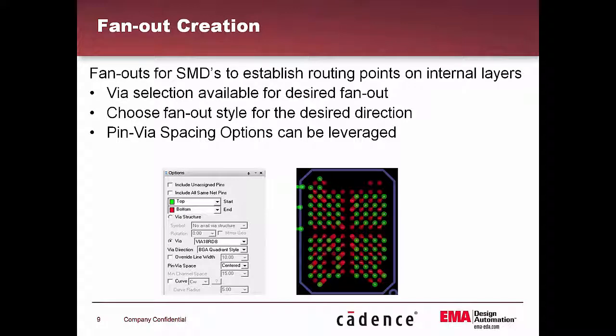In that first slide, I showed you that connector where all of the vias were in a line cutting off the routing channels. Well, the pin via spacing parameter down here, we can also enable this minimum channel space, which helps us open up those type of issues, and I'll show you that in the demo.